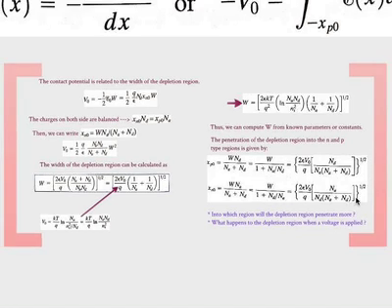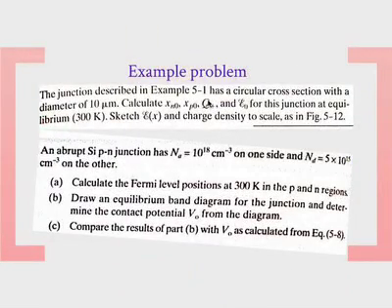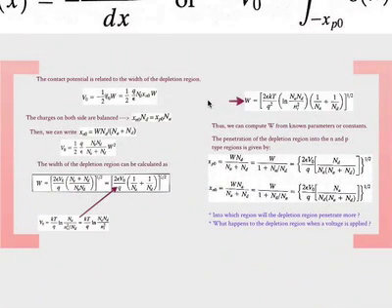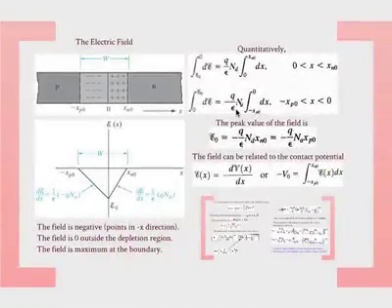Now the next part of the question is what is Q+? It is the total charge. Now remember, the total charge can be related to the contact potential as well and the field. But actually, you don't need to look up an equation. It should be pretty obvious. You know the total charge on this side and this side are equal. Charge here is mostly the donor concentration, the donors who have donated the electrons.